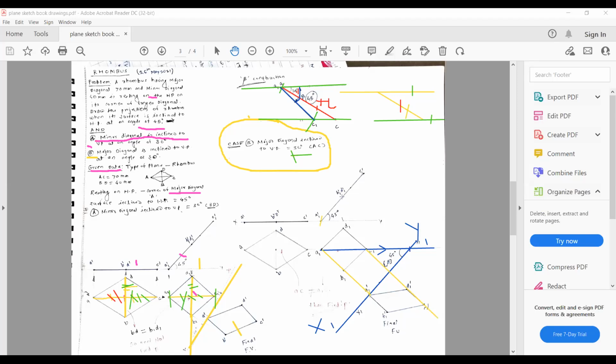B dash D dash, this distance from A, B dash D dash is this one. You take this much distance in the compass, and through B and D, take the distance, cut it here, you will get the point. Take the same distance through D, the extension of D from B, the XY line is this one, cut it, it will give the D point here.